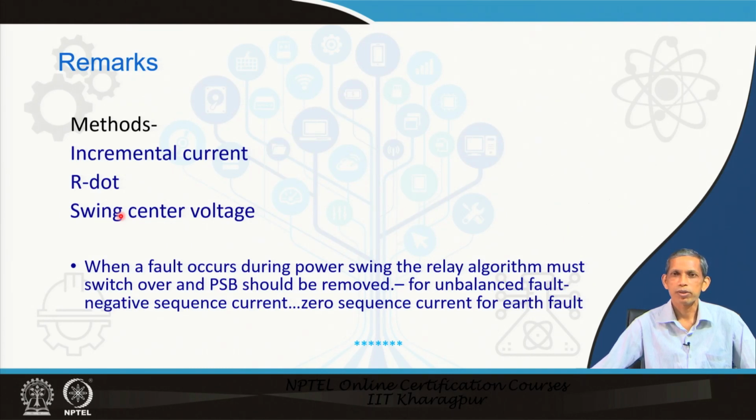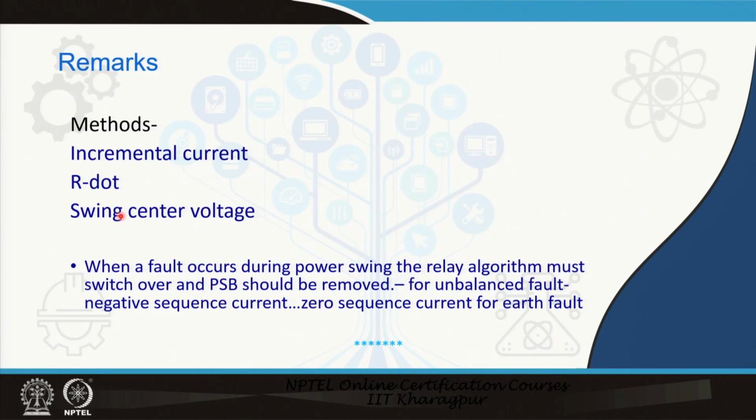For out of step tripping we have to identify whether it is an unstable situation or not, and out of step tripping is accomplished only at predefined strategic locations, not at all locations for the distance relay. Note, there is a probability that a fault may occur during a power swing, because power swing is an elongated process.